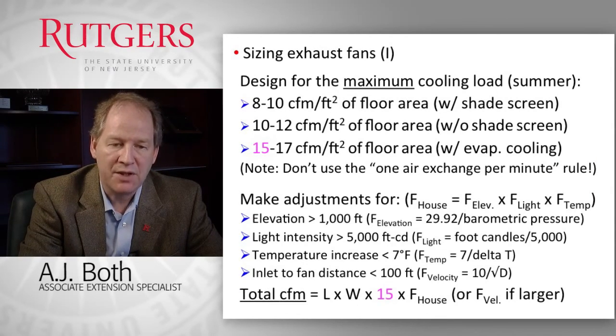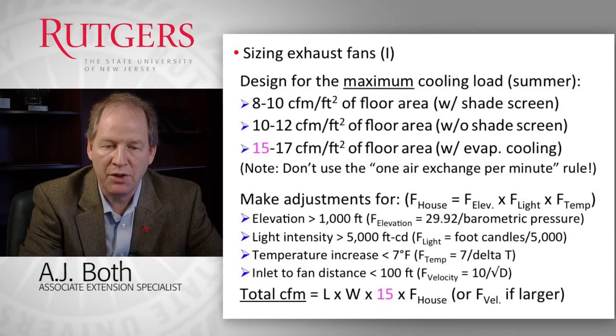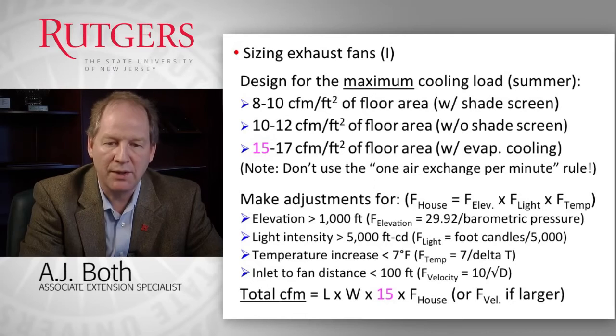When you think about sizing the exhaust fans, we have two conditions that we need to worry about. The first one is the maximum ventilation rate needed for summer conditions, and the other one is the minimum ventilation capacity needed for winter ventilation. So let's first look at the summer conditions. Depending on whether you have a shade screen installed to reduce the heat load on the plants and to the inside of the greenhouse, you have different rates that we recommend.